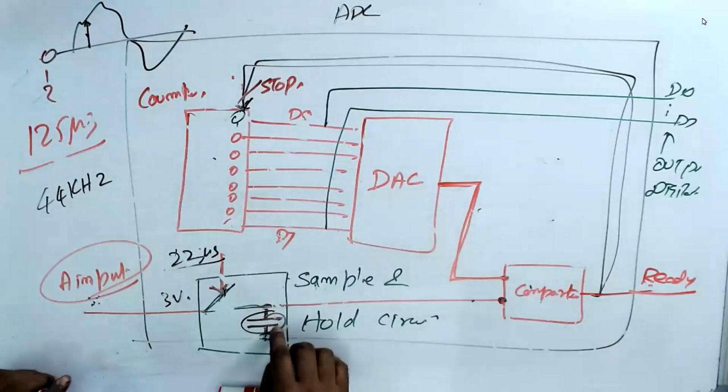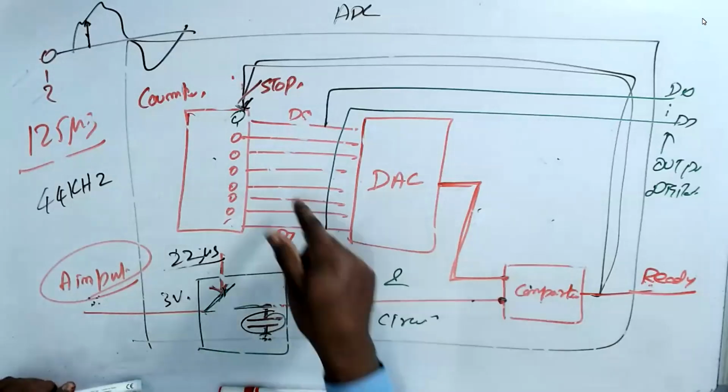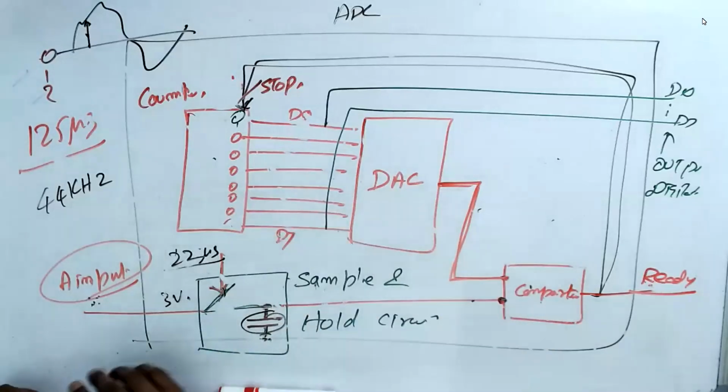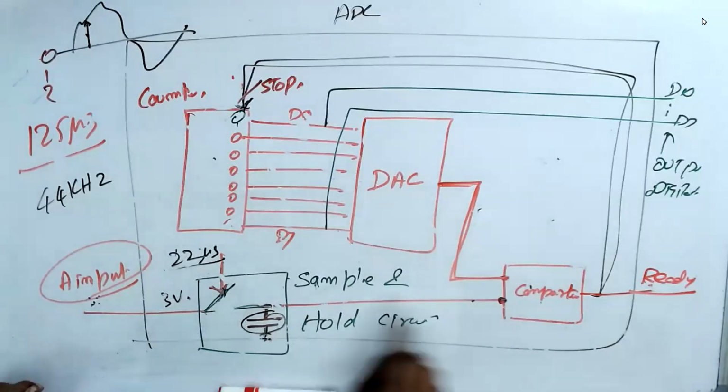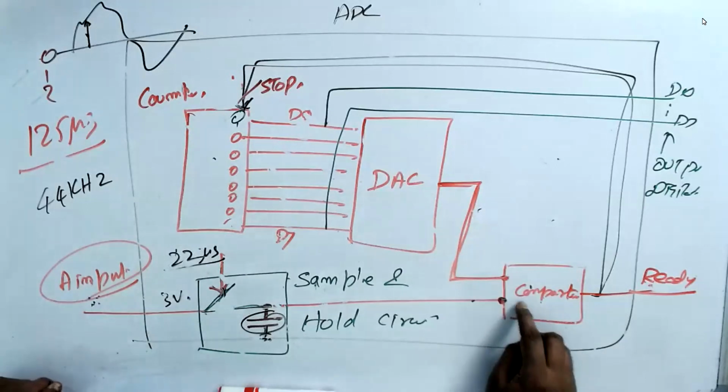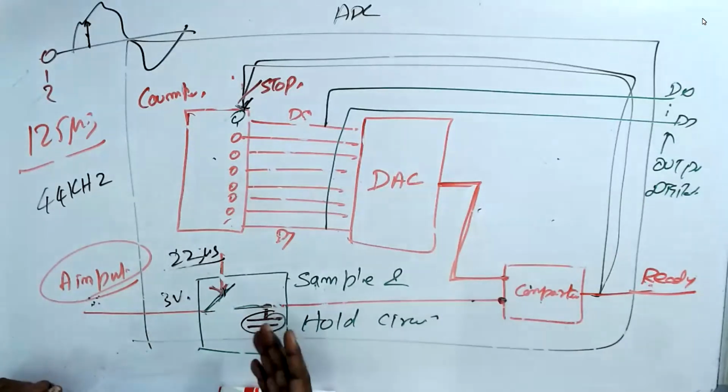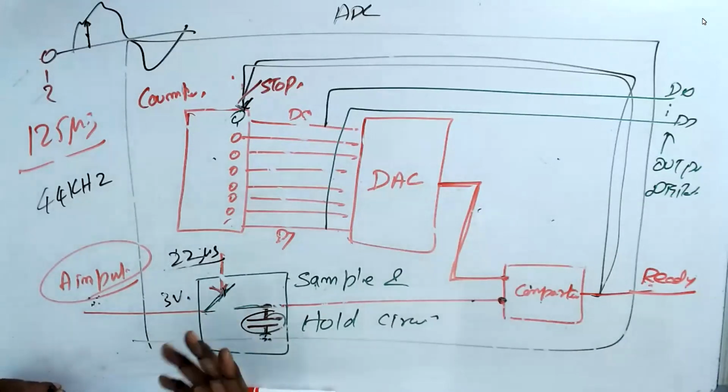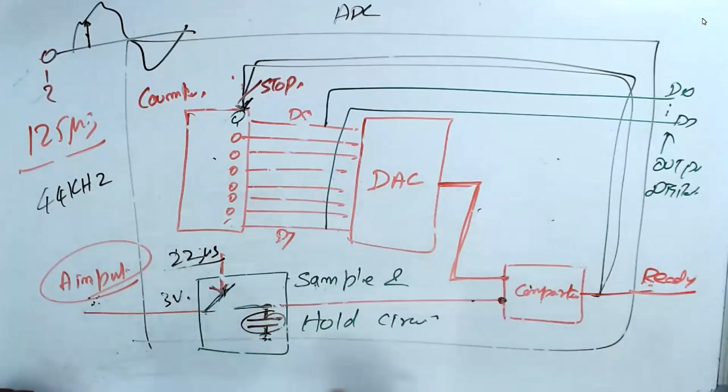Of course, there can be a small leakage, but before that, it will finish. So that leakage, you can forget it. Your op-amp has a huge input resistance, which means the current will be very less. So the leakage will be very low, and we can assume that the capacitor will hold the same voltage all the time. The discharging of voltage will not take place. We assume that right now. Let us go to the ideal case. Anybody who doesn't understand this, let me know.